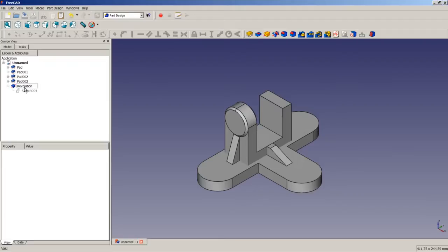If you would have something like let's say cut and revolution and sketch, something with several instances, only the last, or to be more precise, the top 2 instances will be copied to the clipboard.